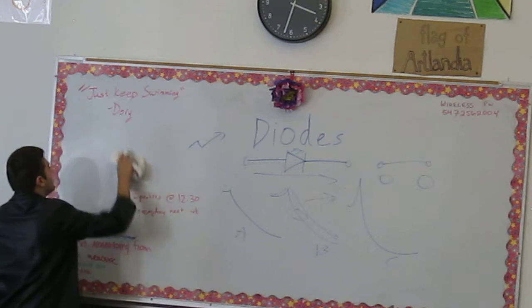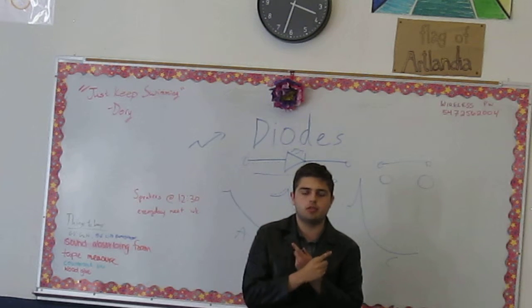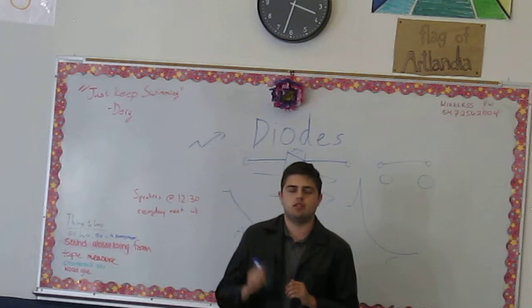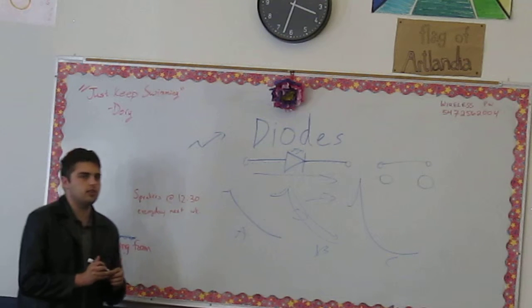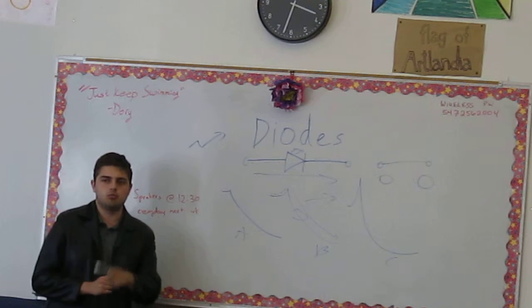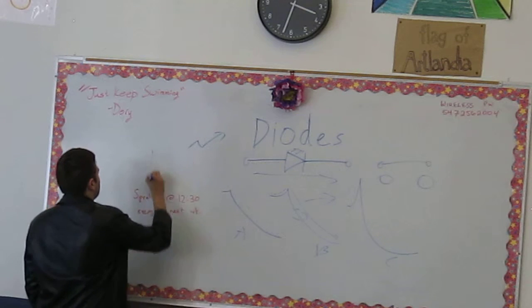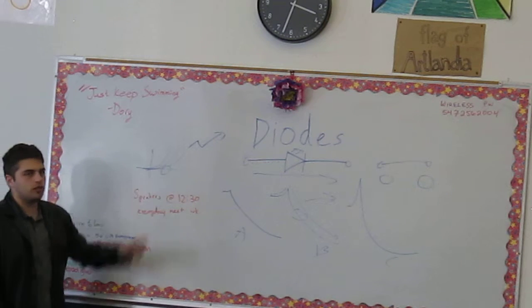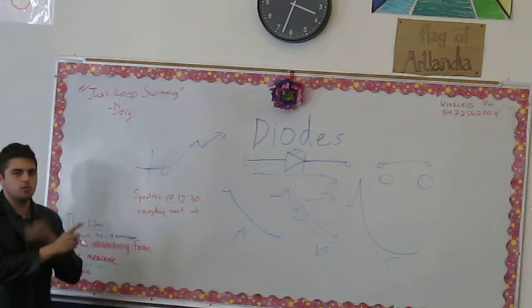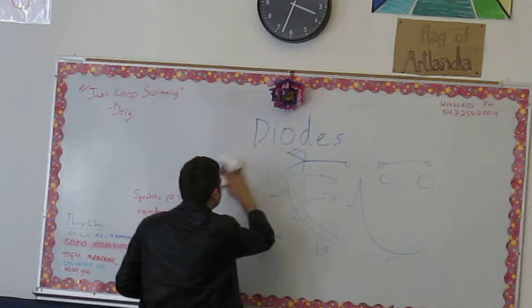So when you guys are looking through your circuit, if something's wrong with it, most likely, like 9 times out of 10, you flipped it around. Something else that could be wrong is you haven't reached VTO. So let's say you've got red, green, and blue LEDs, and your red's on and your green's on, and your blue's not on, and you've turned it on. So what could be wrong? Yeah, because you could be living right here in a land where red and green have turned on, but blue hasn't turned on yet. Or blue could just be put on backwards. You gotta check it out. So that's what's going on with diodes.